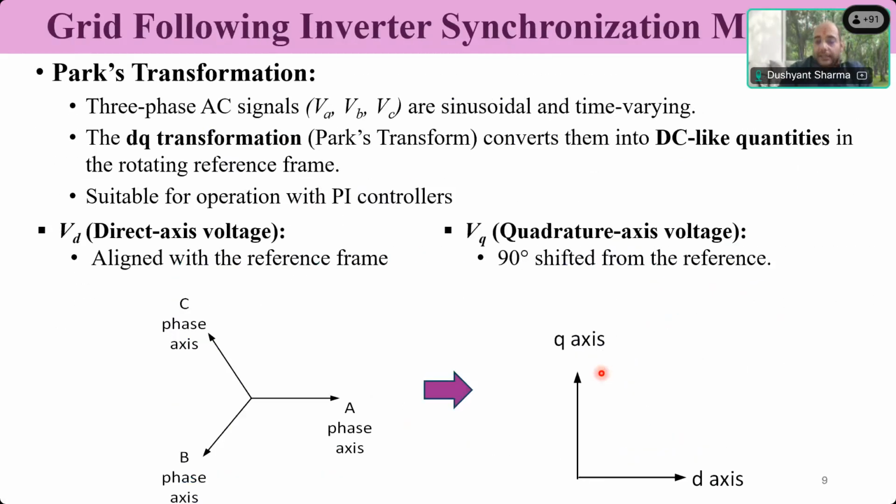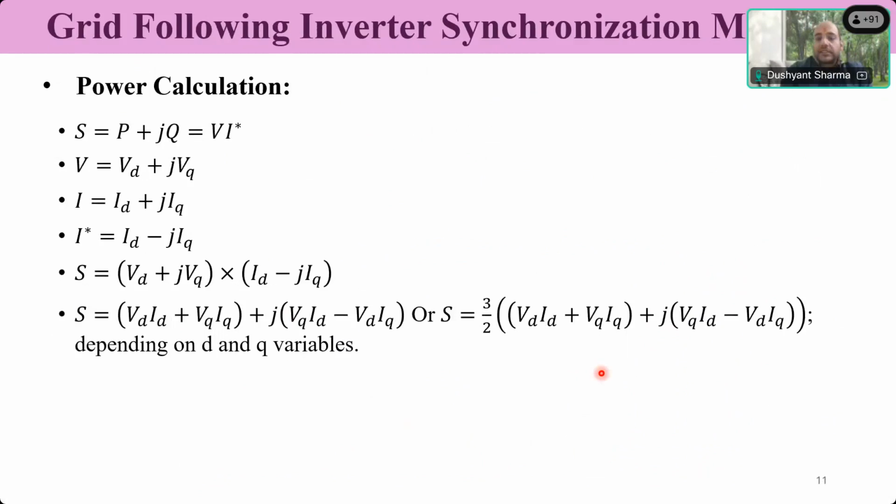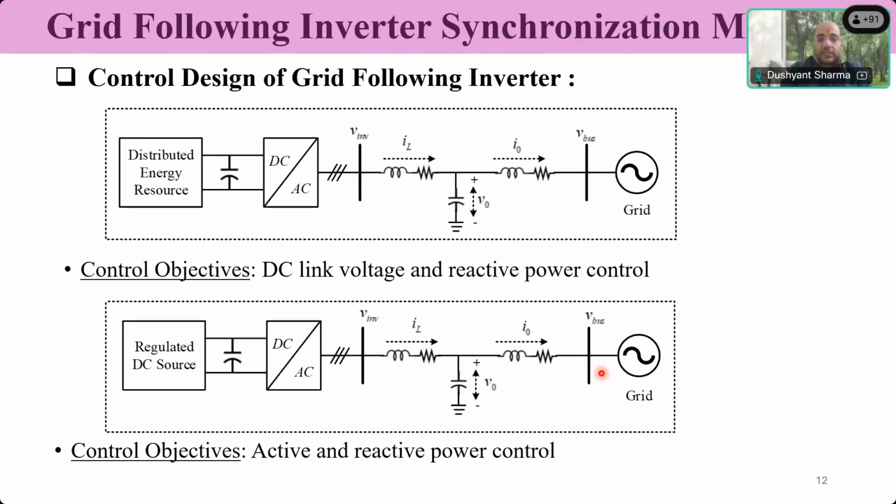Again, that D axis current and Q axis current reference that we get is converted to ABC to generate the PWM, because you know, an inverter is controlled by the PWM. So let me just look at the time. Accordingly, we'll see how much in depth we go, but we will not go into the mathematics of all.